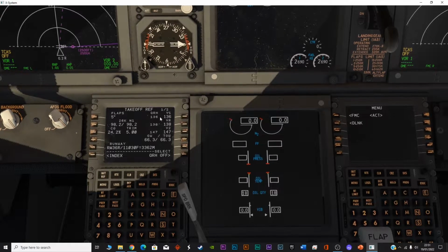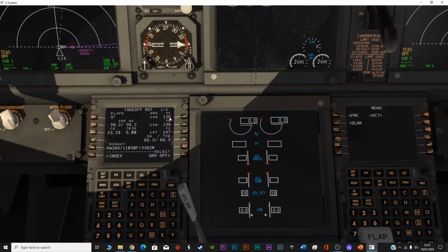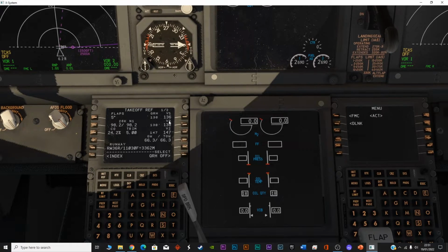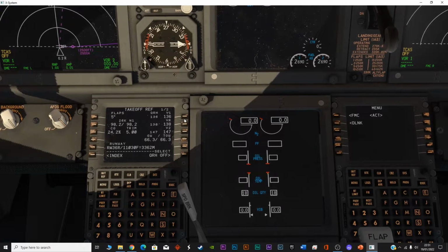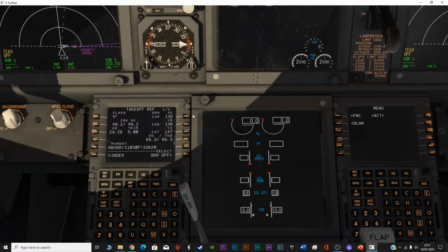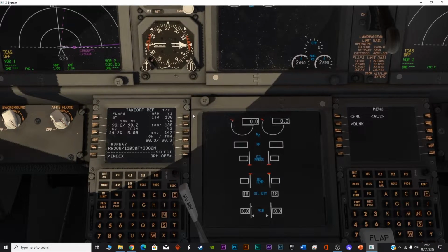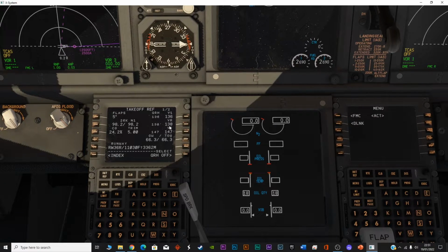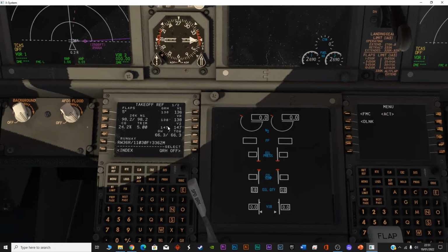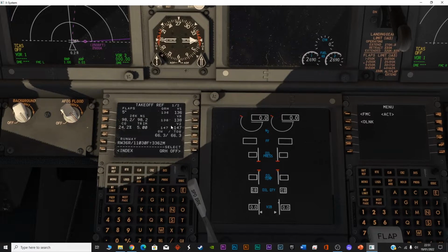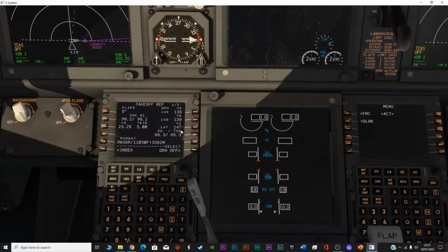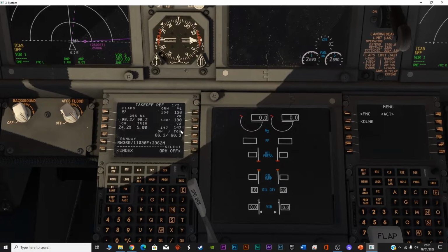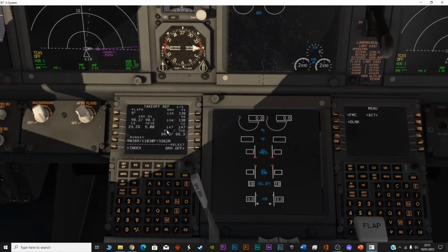But if the speed is above this 136 knots, then obviously you have to take off, or if you abort your takeoff, then it will be very difficult to stop the plane before the end of the runway, so it can be catastrophic. VR is the speed at which you rotate on the stick to lift the plane from the runway, and V2 is the speed at which the plane can comfortably fly on one engine. So your speed should be 147 knots.